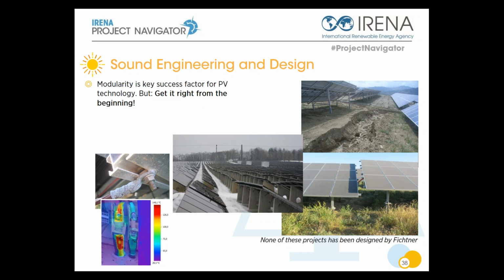The one at the top left picture seems not really critical, but already shows, after 1 year of operation, electrochemical corrosion due to an inappropriate combination of materials. In our practice, we have seen projects with costs in the six digits, a couple of $100,000, just for implementing washers after the plant had been completed to avoid electrochemical corrosion.